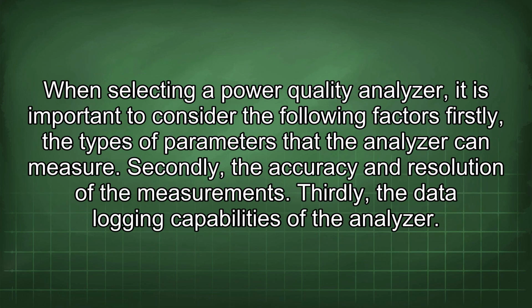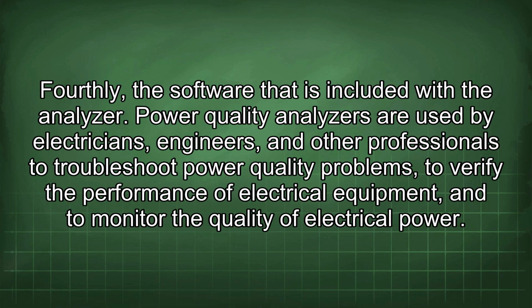When selecting a power quality analyzer, it is important to consider the following factors. Firstly, the types of parameters that the analyzer can measure. Secondly, the accuracy and resolution of the measurements. Thirdly, the data logging capabilities of the analyzer. Fourthly, the software that is included with the analyzer. Power quality analyzers are used by electricians, engineers, and other professionals to troubleshoot power quality problems, to verify the performance of electrical equipment, and to monitor the quality of electrical power.